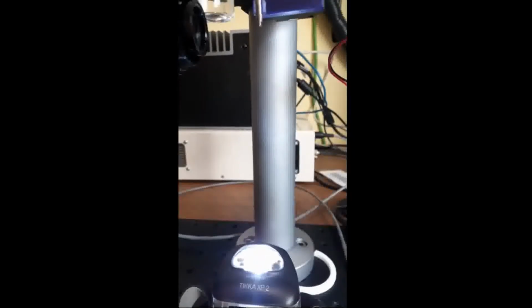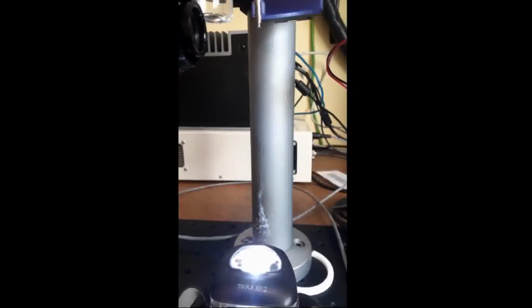It will save you a lot of money on machine shop bills. Here is a test of the injector. Notice the thin drops being thrown about 10 centimeters below the injector. Here is a video from the camera setup with only the strobe LED on, no laser. 33 still images were generated using increasing strobe delay and were assembled into one clip. With the particular waveform, it was generating 3 drops per pulse.